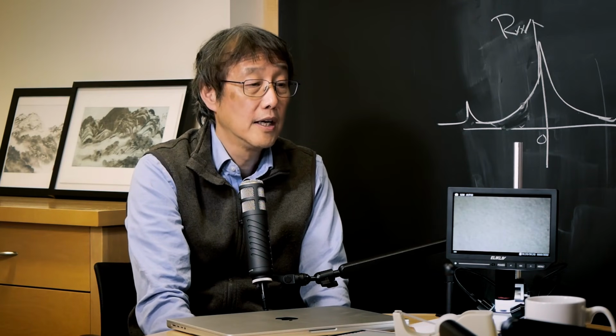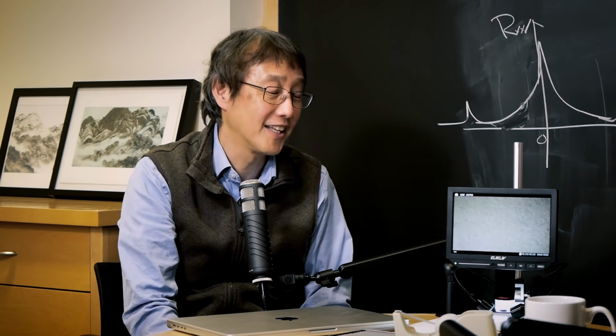But the main issue with this platform is the materials creation, like growing, let's say, indium arsenide and aluminum, a kind of interface. What are the main challenges? I think controlling the disorder. Disorder? Yeah, I think that's always the main challenge. I think it's the case for all quantum material platforms. Because again, you may say that fault tolerant means it's resilient to all the disorder. Yes, but it becomes fault tolerant within this topological gap. To keep it and make it large enough and to suppress all the quasi-particle poisoning, quite a lot of control of the disorder is needed. What kind of disorder? In real materials, there is always disorder. At the interface, there is disorder. Unless you can control every atom, there are always defects, right?